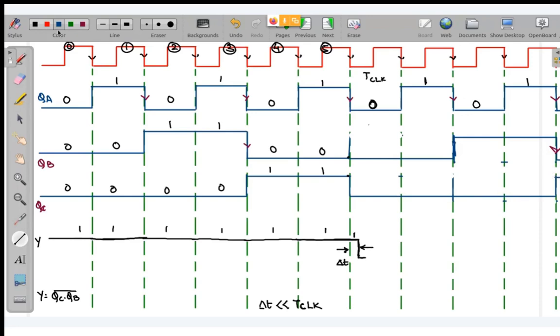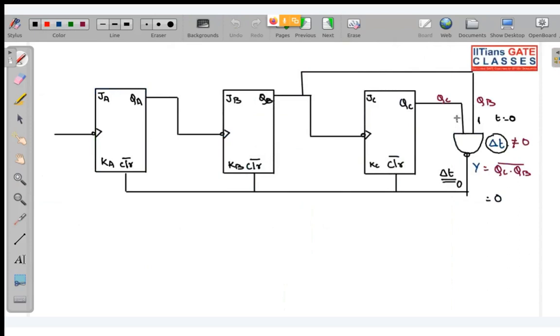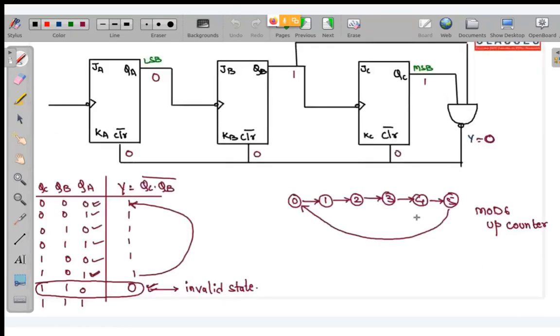And what about this one? So immediately this is momentarily 0. Now you can see over here, as your state is reset to 000, the input changes from 111 to 00, and the moment this becomes 00, this y will become 1, but it will become 1 after del t seconds after your application of input.